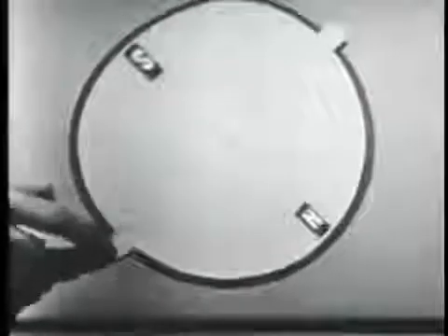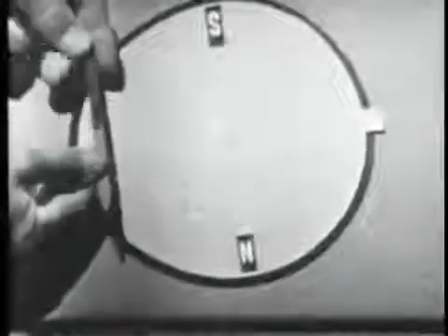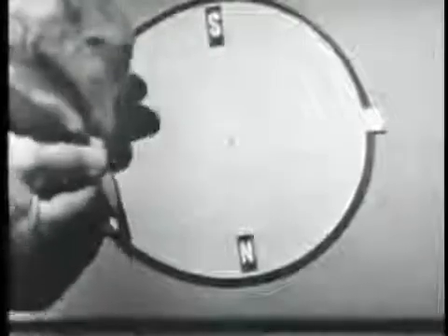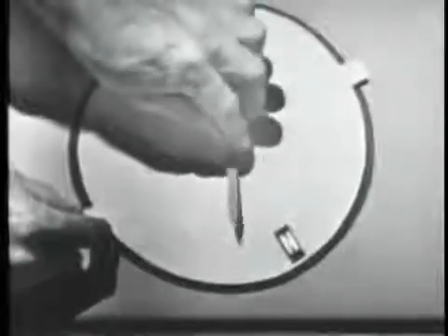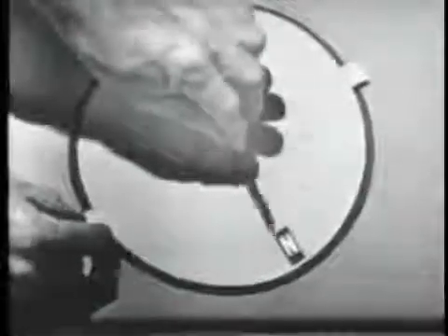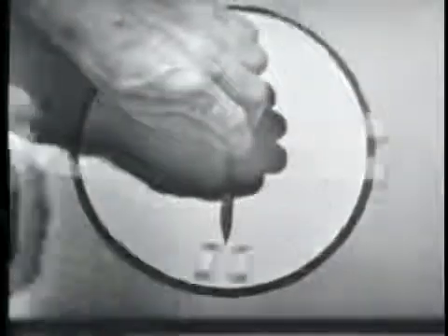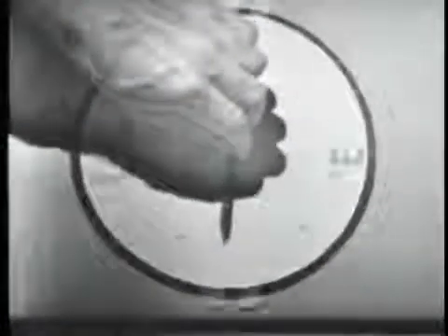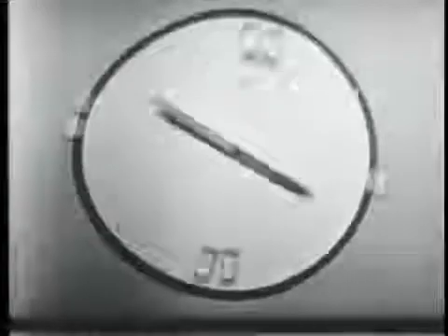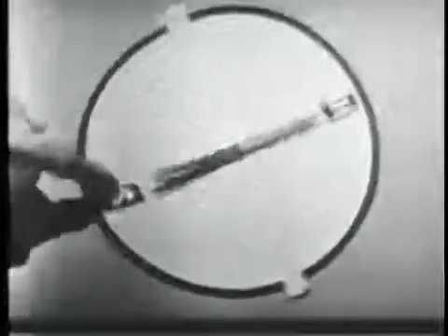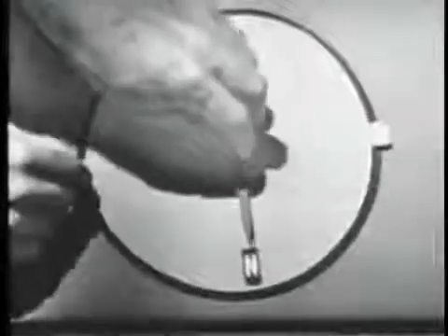Thus, if we spin the disc, we have a rotating magnetic field. Now, the principle we want to show you here is that if we take another magnet, such as this compass needle, and put it on the pivot, so it's free to rotate, and we spin the cardboard disc, we have a rotating magnetic field. Now, you'll notice that the compass needle picks up the rotation of the rotating magnetic field, tries to align with it. Now, this is an extremely important principle.